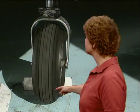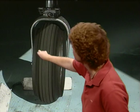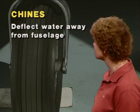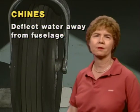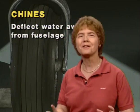Let's talk now about aircraft wheels and tires. And let's start with this interesting nose wheel tire off of a Citation. You'll notice around the edge of the tire there's a little lip of rubber that extends on each side, and that's called a chine. The purpose of the chine on a nose wheel tire is to help deflect water away from the fuselage. So as the airplane is on a takeoff or landing run, water will tend to be scooped off to the side and deflected away from the fuselage, and the idea behind that is it reduces water spray going into the engines.